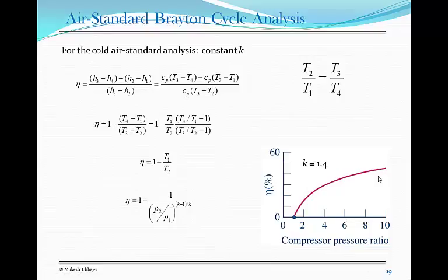Keep in mind the quantities given in table A22, PR and VR, are relative pressure and relative volume. They are distinct from the reduced pressure and the reduced volume that we defined in chapter 3.